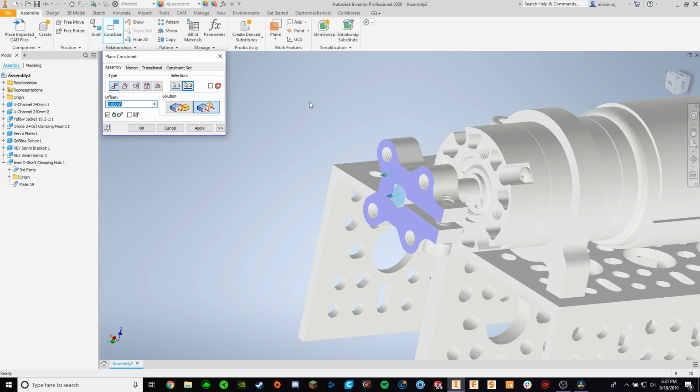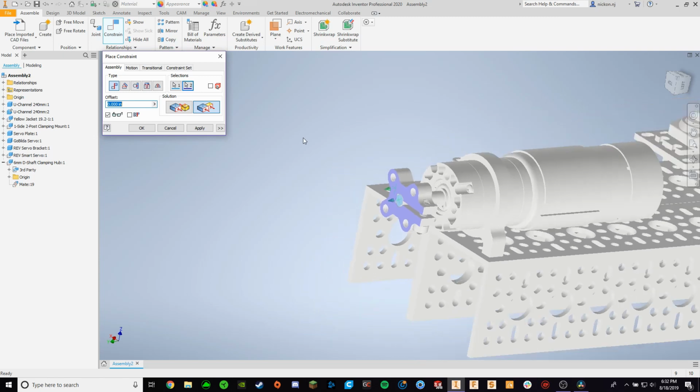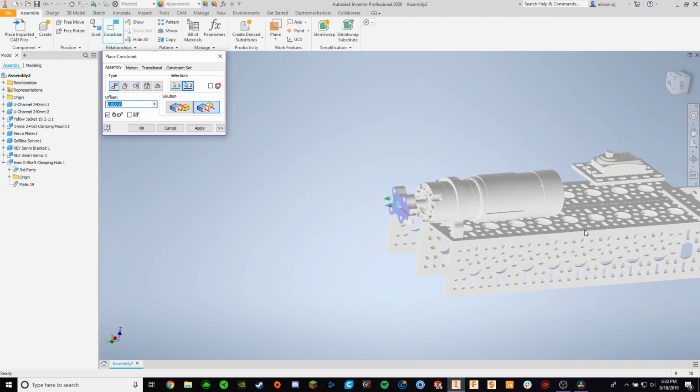There's a few things that are like that as well. Sprockets, for example. CADing chain in Inventor that works, I think, is next to impossible. I don't think I've seen anyone ever do that. In SolidWorks, it's a bit easier to do, but it's still really, really advanced, CADing the chain links and they all move together. What you should do is just put the sprockets and leave the sprockets empty. Same thing with a belt as well.